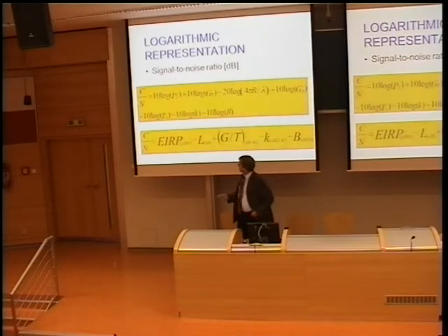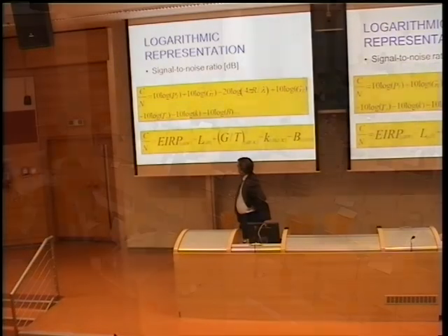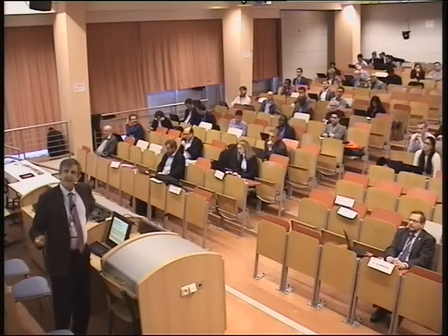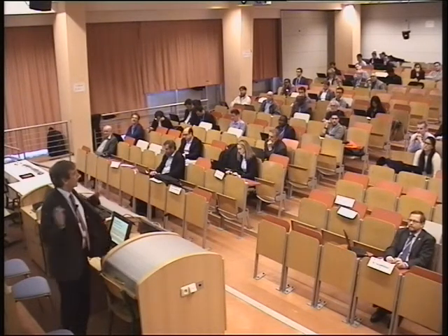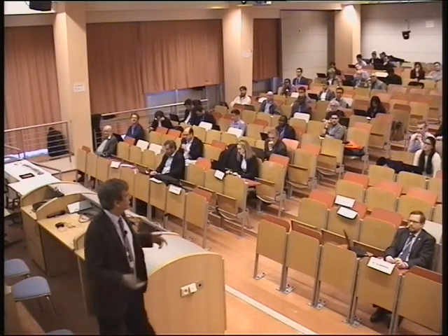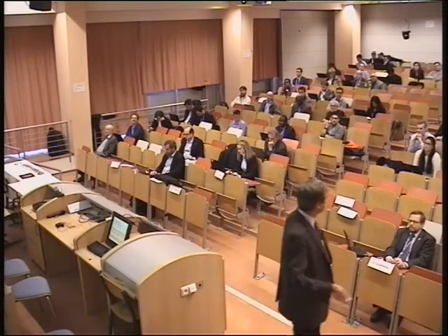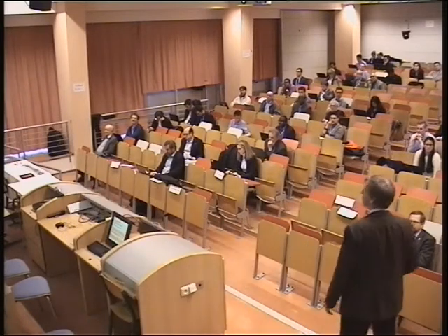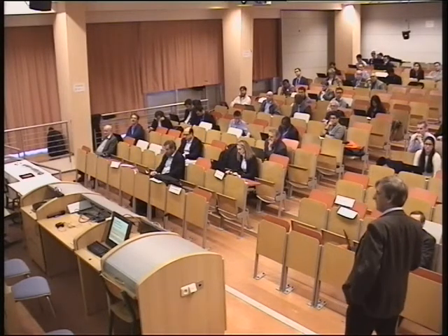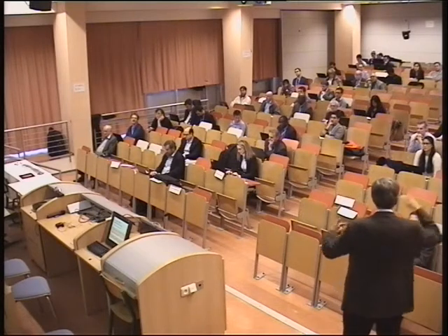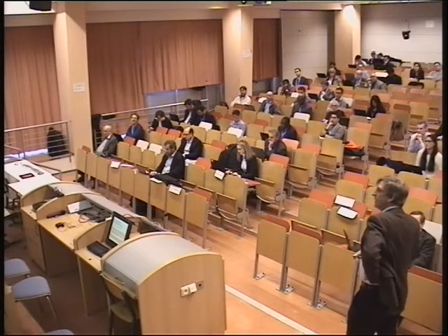So basically, our signal to noise ratio is given by the EIRP of the ground station. The free space loss is given: when we choose the frequency and we have the distance, we can't do anything about it. But there are 2 parameters in our ground station, going from ground to satellite, where we can fiddle around.